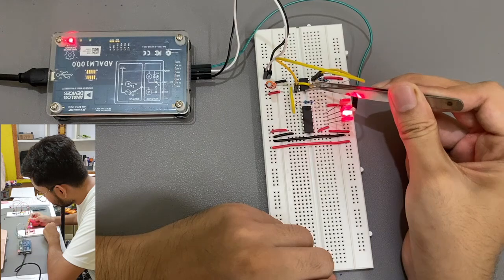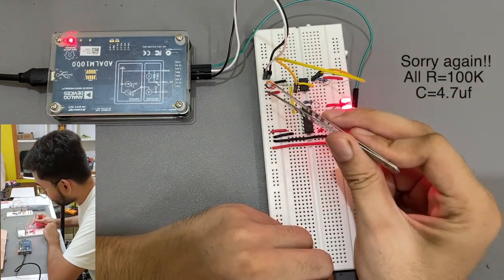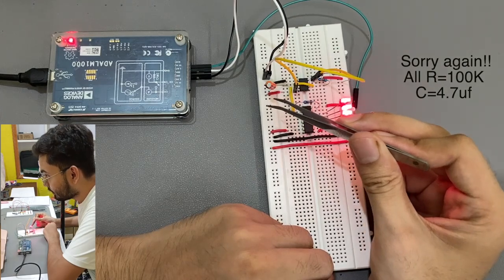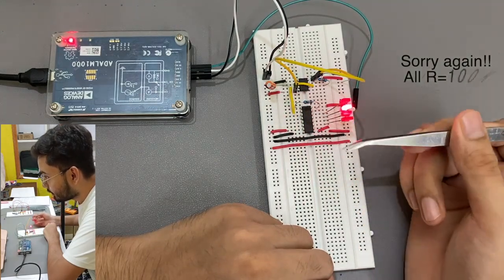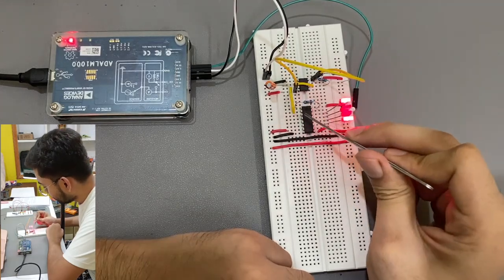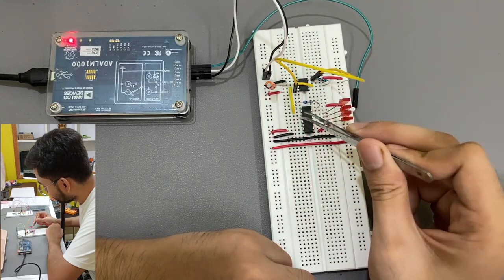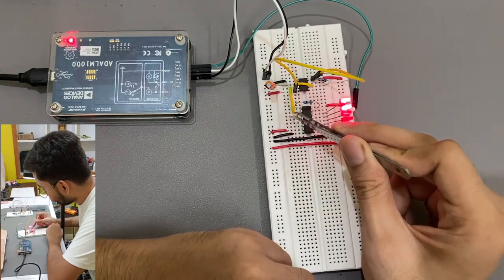Here in the 555 timer IC, I am using two resistors of 1 kilo ohm and one capacitor of 4.7 microfarad, because for astable operation as an oscillator, the free running frequency and duty cycle are accurately controlled with 2 external resistors and 1 capacitor. This resistor between the first and 16th pin of 74LS163 is not making any difference. We can connect a wire also.